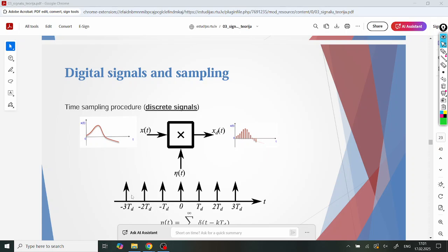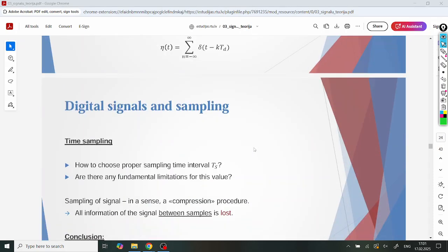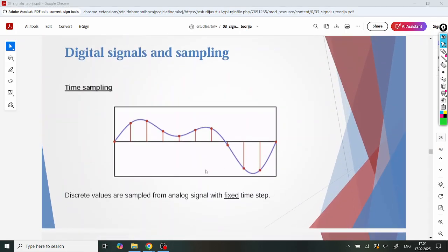strong pulses. So each of these pulses is going to be multiplied by a signal. In between the pulses, there is zero. Zero multiplied by signals produce zero, and essentially you end up with this signal, which is now a sampled version of the signal. So here you can see the bigger picture of this. We take readings. We don't do anything about amplitude at this point because we deal only with a discrete signal at this point. Digital signal will have quantizing applied to it as well.